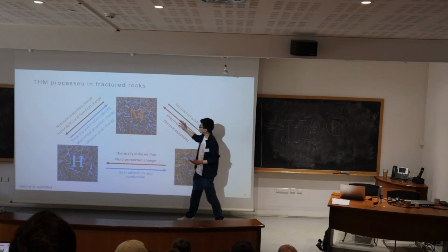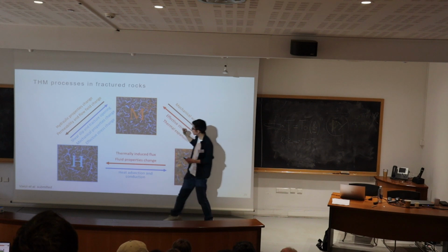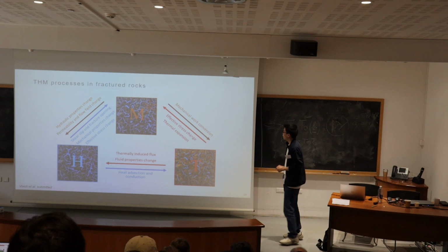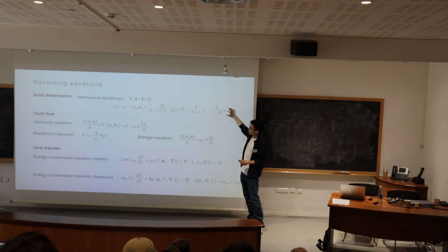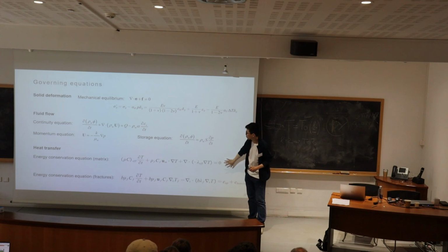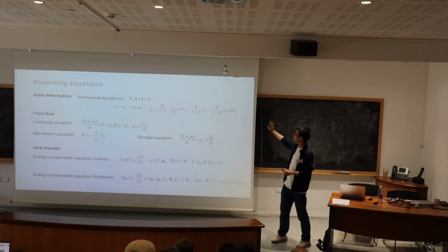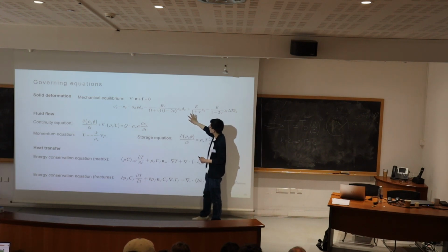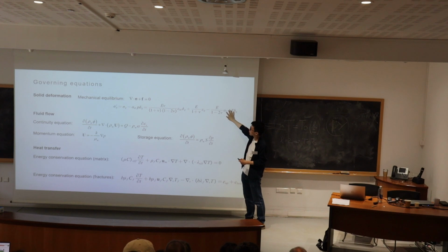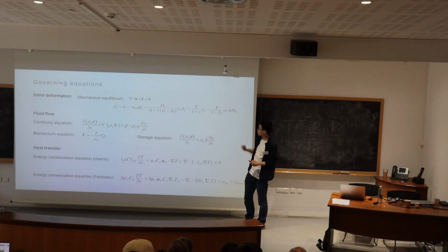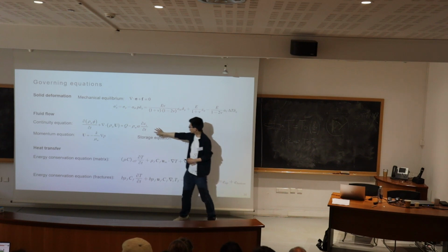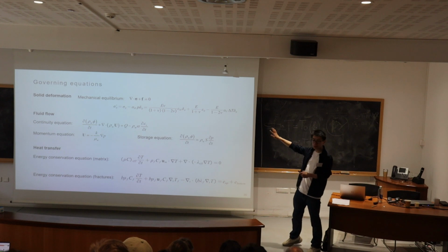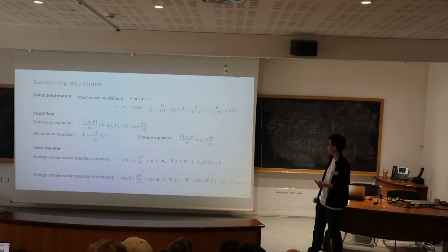Here, the thermal, hydro, and mechanical processes are interrelated with each other. They can be described by fundamental governing equations, from solid deformation to flow to heat transfer. They can also be coupled with each other through, for example, the thermal expansion we consider in the solid deformation model, and the volumetric change we consider in the fluid model. This allows us to link these different governing equations together.